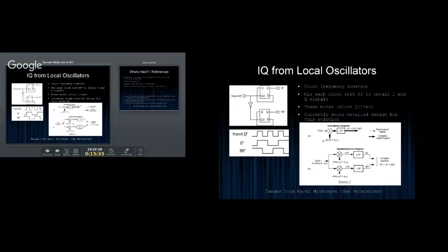You invert the square wave, and the toggle of the D flip-flops or the D latches are triggered by the rising edge. So if you've got an inverter, then you're effectively toggling the top flip-flop on the rising edge and the bottom flip-flop on the falling edge. And then you generate waveforms that look like this.